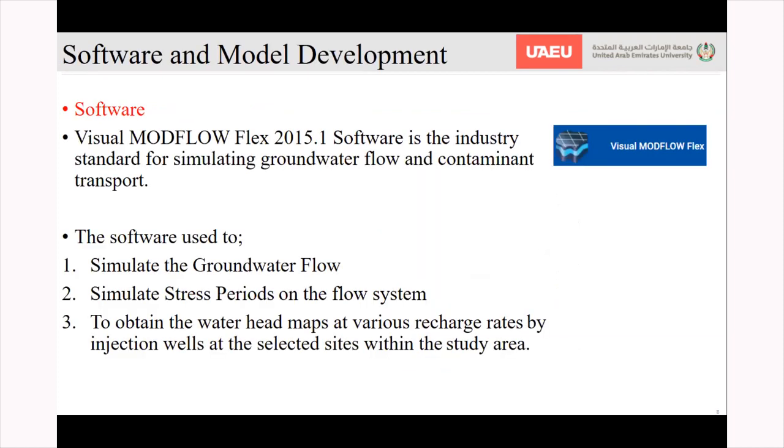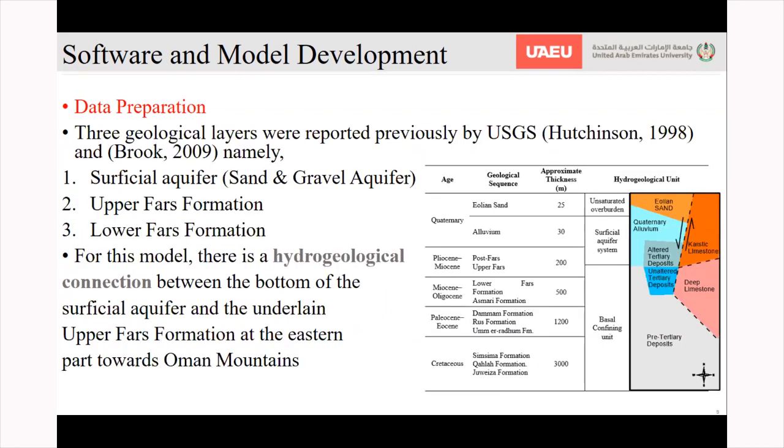So we used MODFLOW to model the groundwater in these 2 sites and check if they are suitable for aquifer storage and recovery in this area. We used the software to develop the model for these 2 areas. So we had to prepare the data, including all the geological and hydrogeological data required for the model from old reports and old publications.